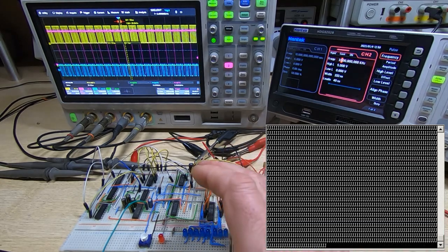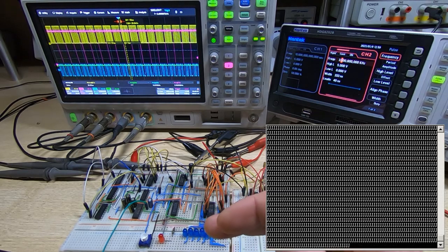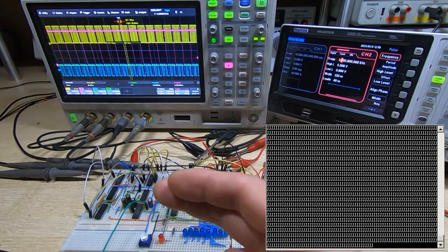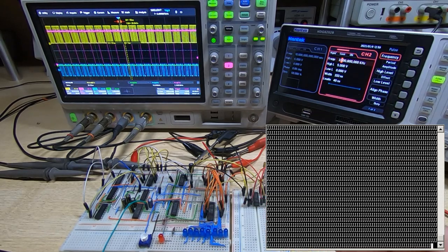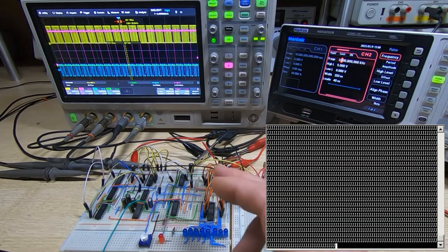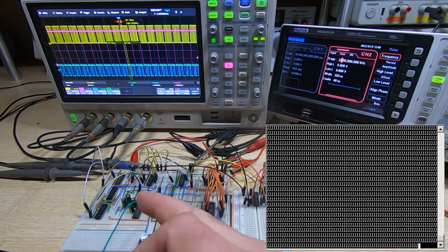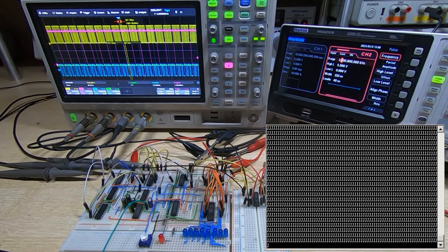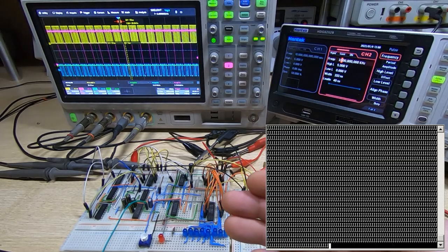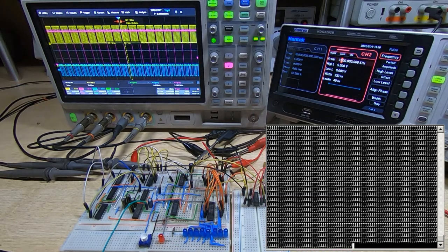Because the system is so efficient, the only thing the Z80 has to do to load the data into it is just write a value out to a single port address. That will not only load the correct value into the shift register, but it will also start the transmitter running. So a single instruction is all we need from the Z80 to load and start the transmit. Much more efficient than using a UART or a PIA and UART combination.